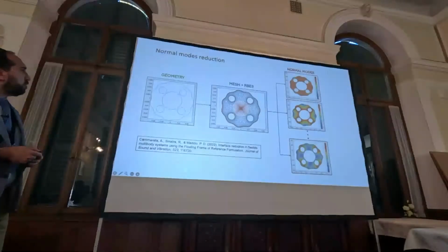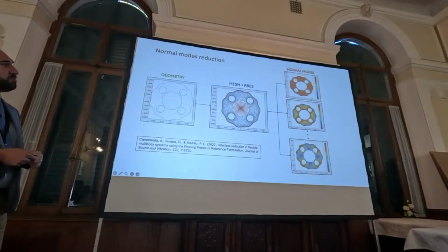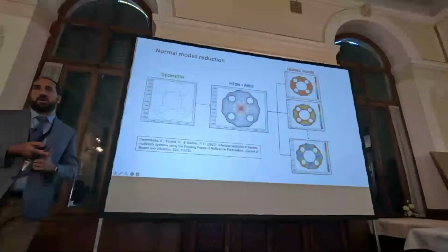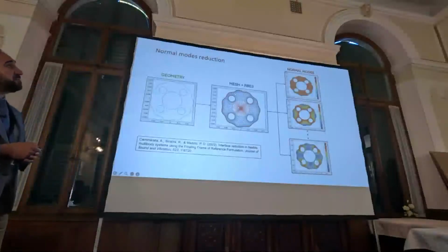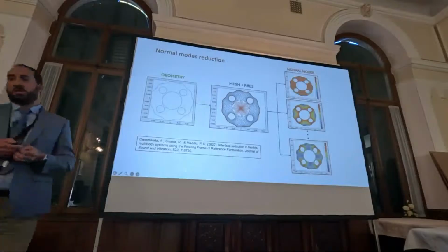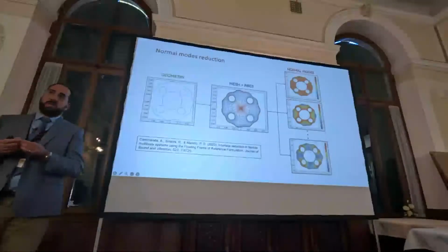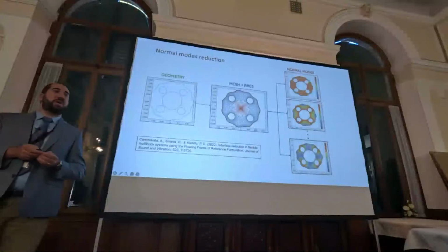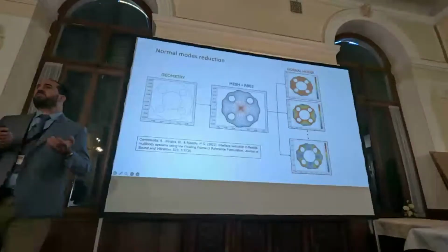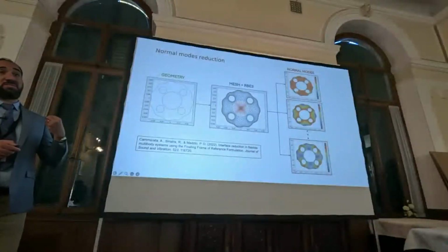So we have to prepare each component. We have to discretize, and we have to find all the invariants in order to find the mass matrix and the stiffness matrix. After that, we also reduce the system, because using the floating frame of reference we have small deformations, and with small deformations you can provide the reduction by using, for example, normal modes. That is just one solution; you can also choose different modes.